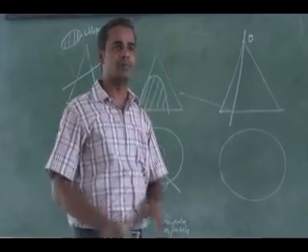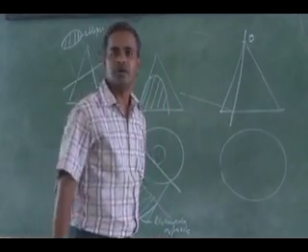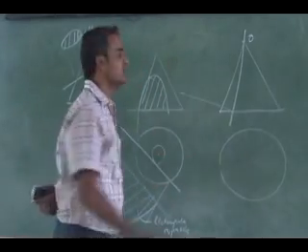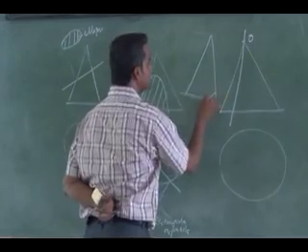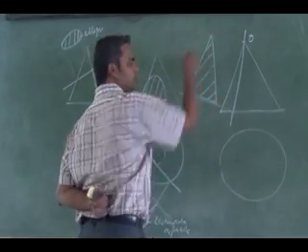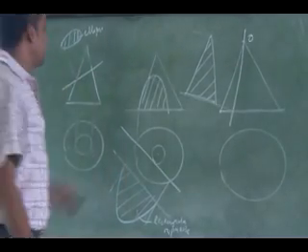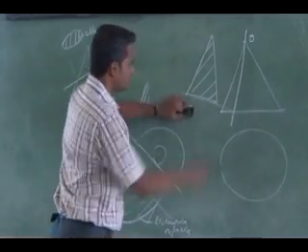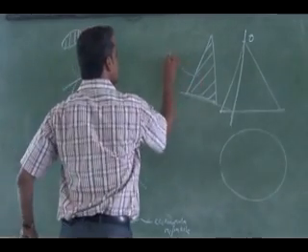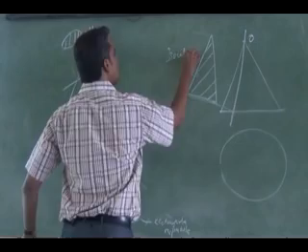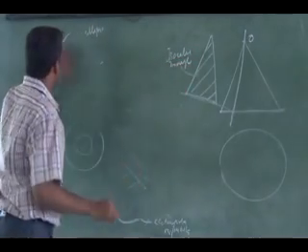So what will be my true shape? If a cutting plane goes through an isosceles triangle, we get an isosceles triangle as the true shape. So I will have only three cutting points. This is the one you should remember. This is an isosceles triangle.